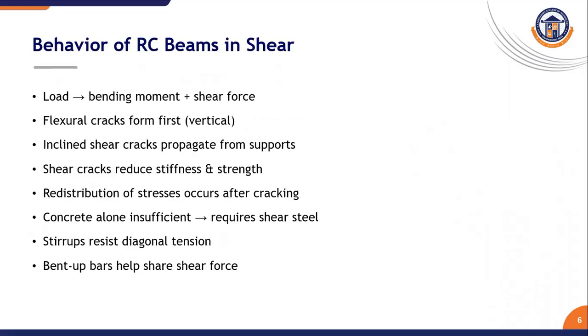Behavior of RC beams in shear. In beams, flexural cracks form first, followed by inclined shear cracks forming near the supports. This reduces the strength and stiffness, and concrete alone cannot resist them. Stirrups carry the diagonal tension and bent-up bars share the shear force. Proper detailing ensures ductility and helps control the crack width effectively.